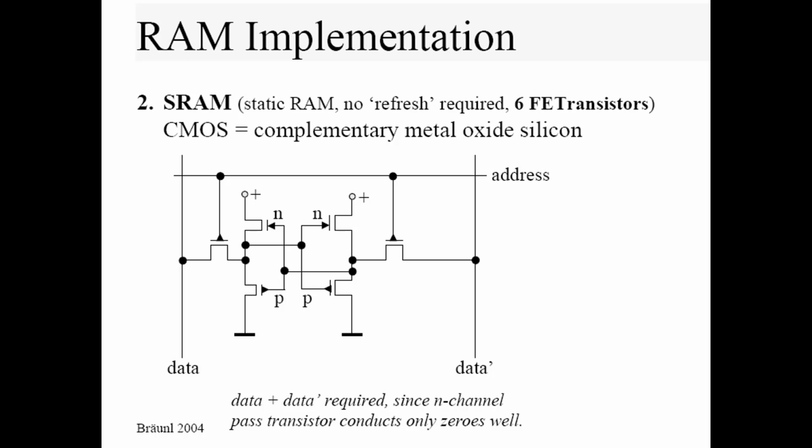Here is a detailed explanation of how it works. In terms of the components, the 6T SRAM cell consists of the following: two cross-coupled inverters. Each inverter is made up of two transistors, one NMOS and one PMOS. Two access transistors. So these are NMOS transistors that connect the cell to the bit lines during read and write operations.